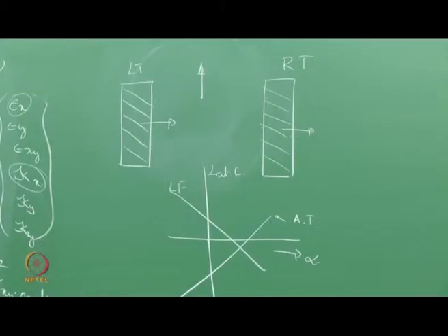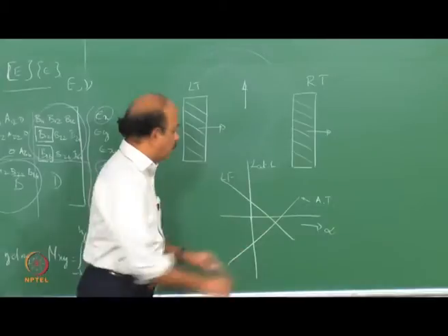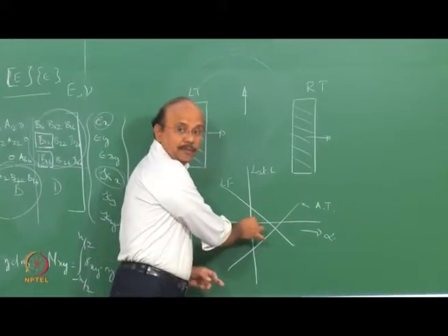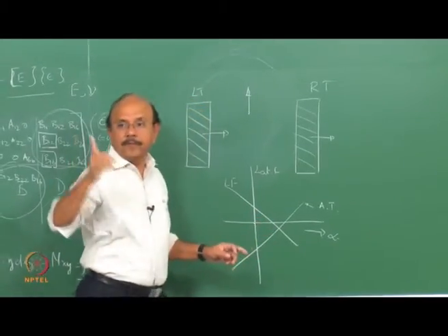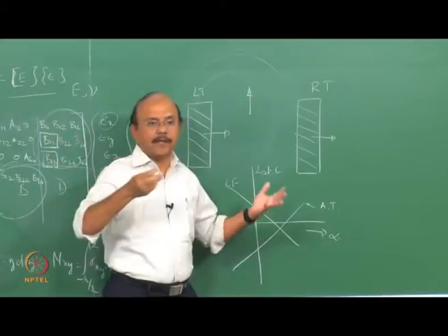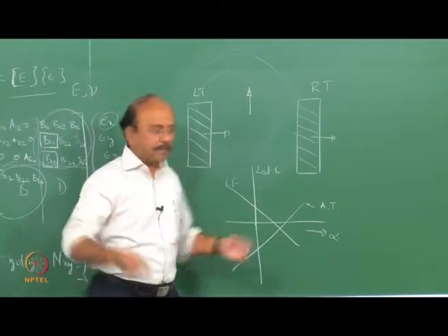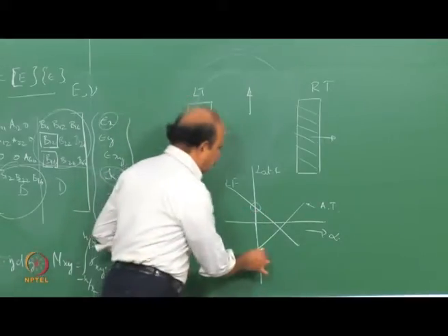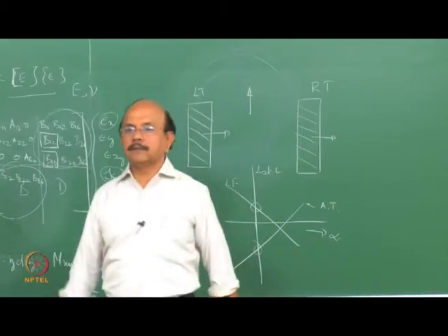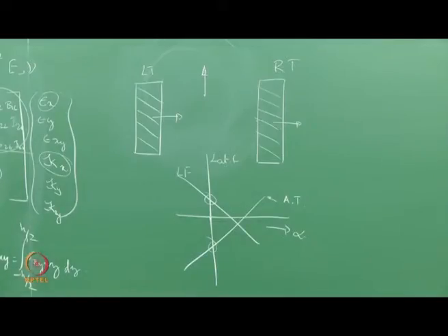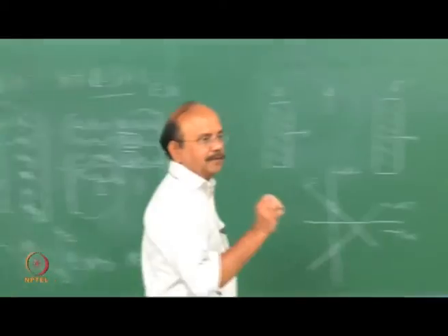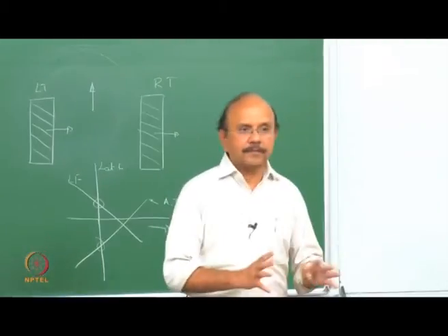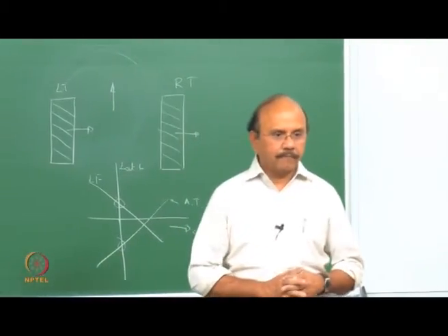And these are, in other words, when they are 0, not when alpha is equal to 0. In other words, when alpha is equal to 0, what is alpha? Slip angle. We said slip angle alpha is required in order to produce a lateral force. So when it is 0, you would see that there is a lateral force and a corresponding moment. Clear? Hold this for a minute. We're going to come back to this graph. I'm going to explain it again.